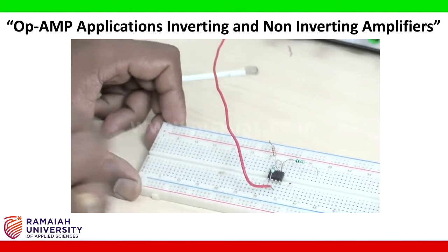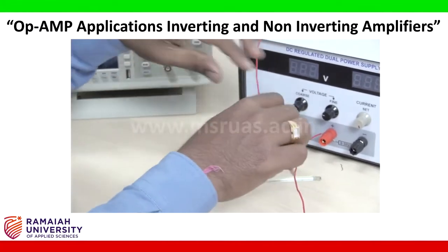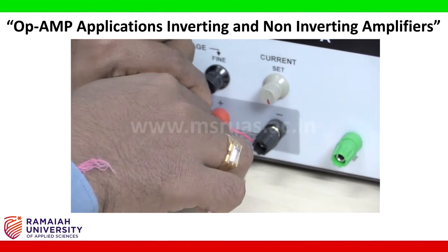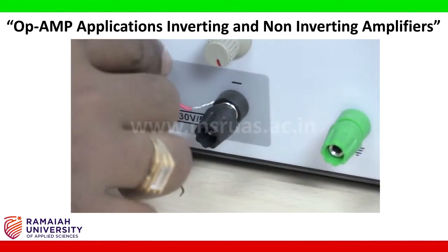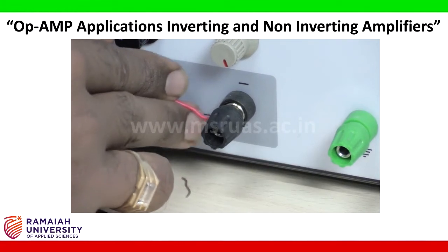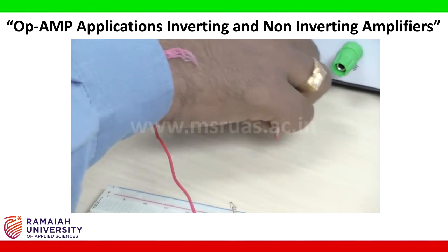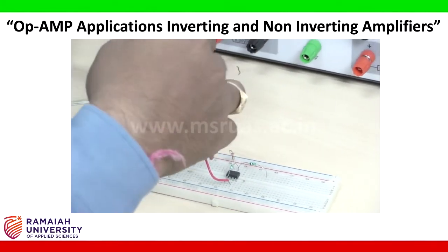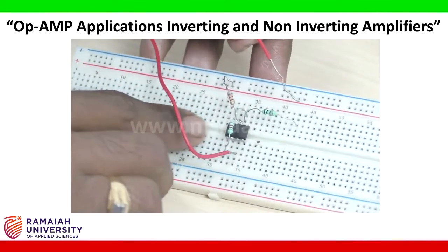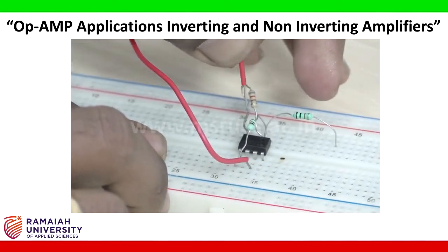This is 6. Now you take the negative supply voltage, which will be connected to pin number 4. You see, pin number 4 is here. I am connecting that to pin number 4.